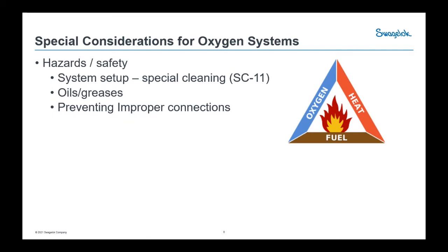You also want to consider your tubing as well. You want to make sure your tubing's inner diameter is smooth bore, because even that microscopic roughness that comes with the stainless steel, or whatever your tubing material is, can create potential points where particles can strike and create sparks. Another good way to avoid that would be to prevent any sort of improper connections to oxygen. Making sure your lines are properly tagged. I've seen an example of a customer who switched all their oxygen lines over to left-handed threads because someone hooked a grease gun up to one before, and the result was not good.